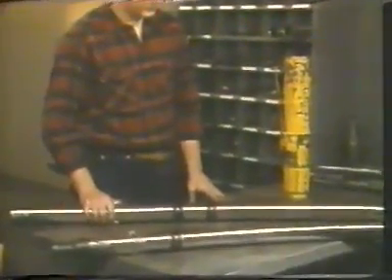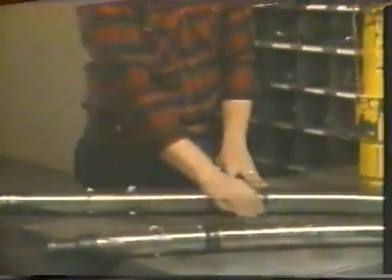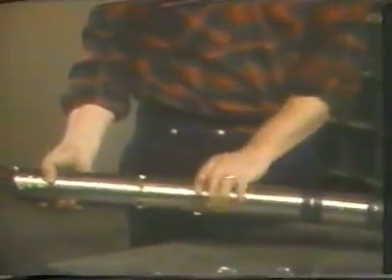Another control device, the subsurface safety valve, is placed in the flow stream of many wells for protection against uncontrolled flow in the event surface flow control equipment fails or is damaged. In such cases, the subsurface safety valve is designed to close automatically. The wireline retrievable safety valve is run and retrieved using wireline methods. It may be surface controlled or subsurface controlled. The surface controlled valve is run in conjunction with a lock mandrel to a special safety valve nipple.